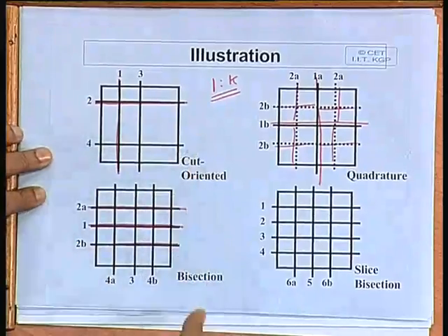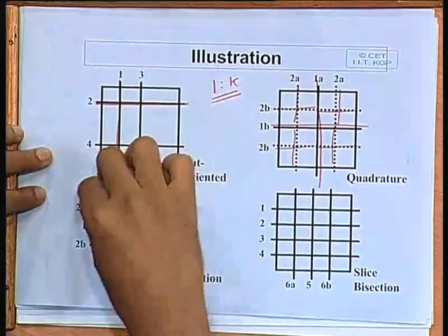If you also do the partitioning of the original net at the same time, you know which subcircuit you will have to put in which standard cell row. Then you try to map the corresponding netlist using technology mapping from cells of the library. Then you do vertical cuts, and place them along the rows in suitable points.